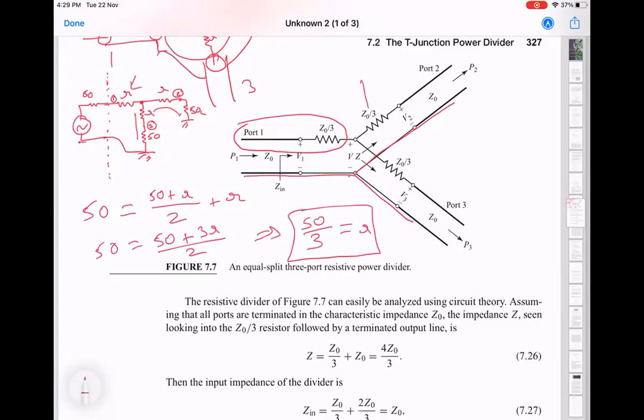Right. So this is basically what they have chosen here. This Z0 is like an effective Z0? Sorry. So, okay, I think I've confused you a little bit because of the nomenclature. They already started in this figure, which is there in the book. They already started with the solution, and then they show you that that solution is the correct solution. I've chosen a general value of R, small r. So R is Z0 over 3. That is basically what I have found. Z0 is 50 ohms. They are just saying that this is true for any generic characteristic impedance as well.